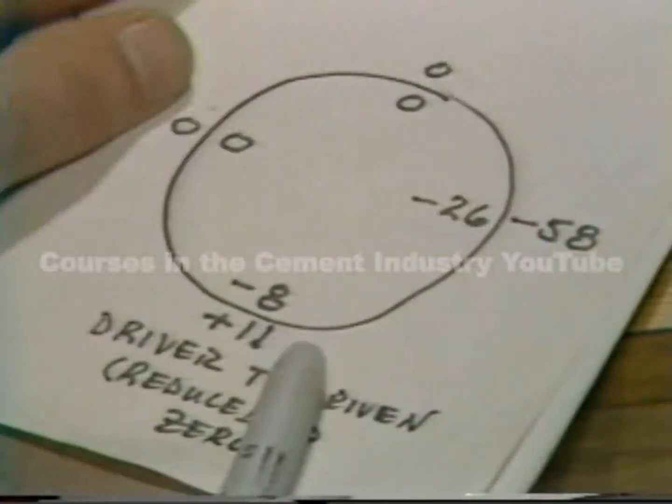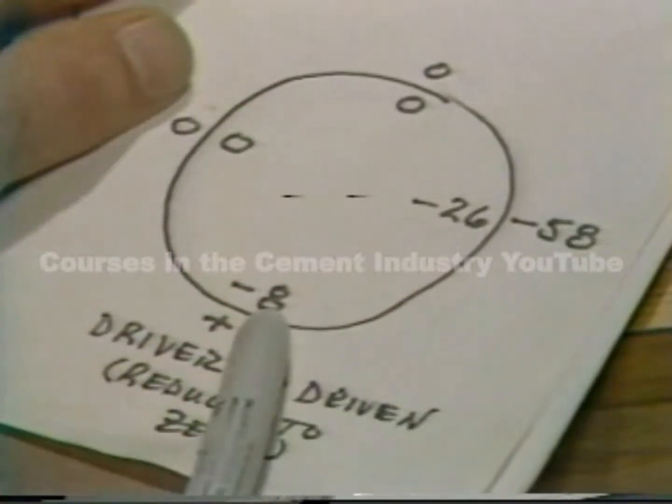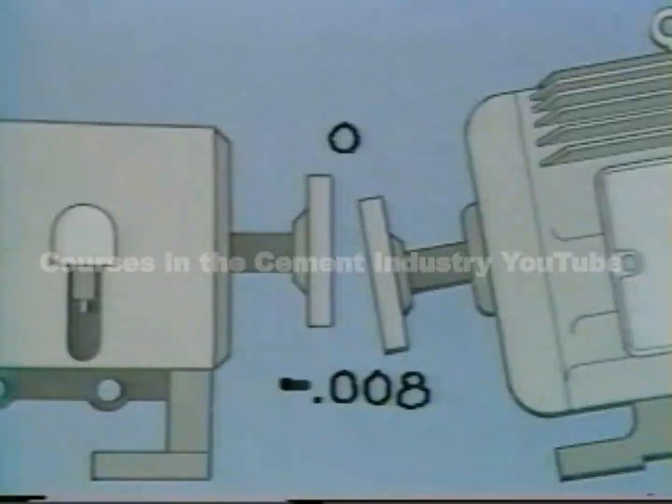Looking at the data sheet, we see that the angular dial went from 0 to negative 8 thousandths of an inch from top to bottom. What does that mean? Let's look at a sketch to see. Since the angular dial moved from 0 to negative 8 thousandths of an inch from top to bottom, the motor shaft must have moved away from the pump shaft by 8 thousandths of an inch. So the exaggerated view of the two shafts from the side is like this, an obvious angular problem.